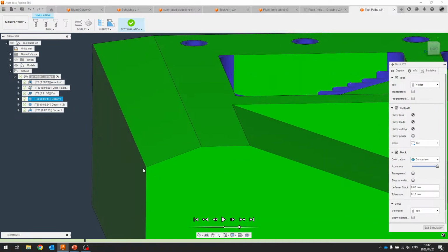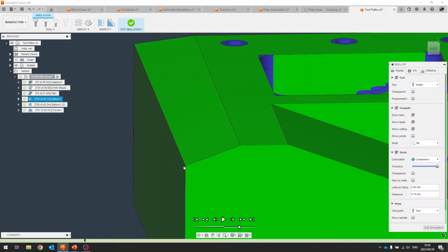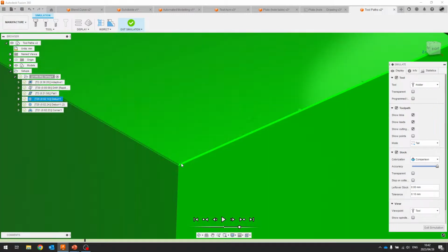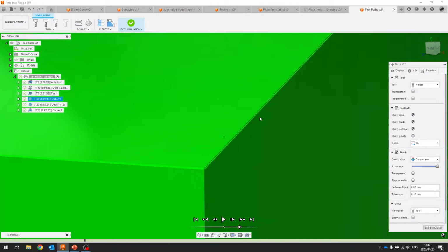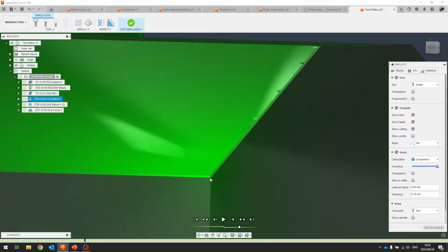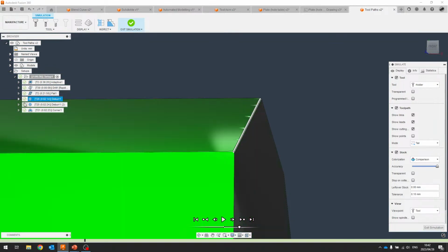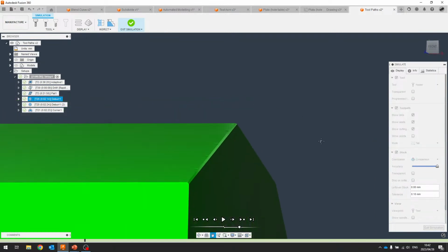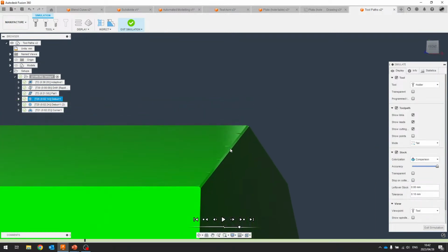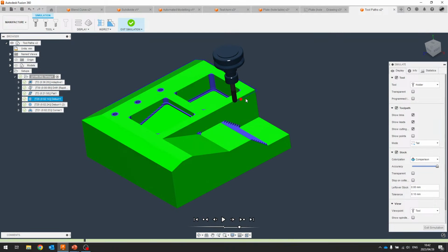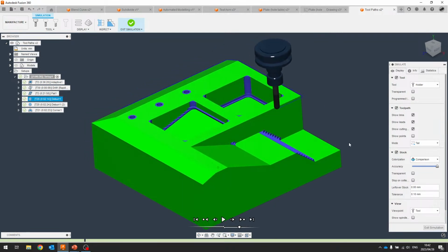Let's push the accuracy up here on the comparison. And this lighting's not playing part, but we can see that edge of material that's being removed. So there we can see, and this would indicate as a small gouge. So if I switched the model off, I think my tolerance is a little bit too big here, but that may indicate as a small gouge in your simulation when you're in comparison mode, because technically you are gouging the part when deburring, however it is by a small amount.